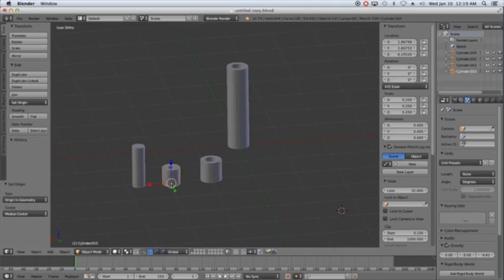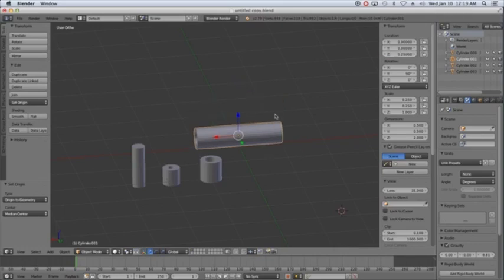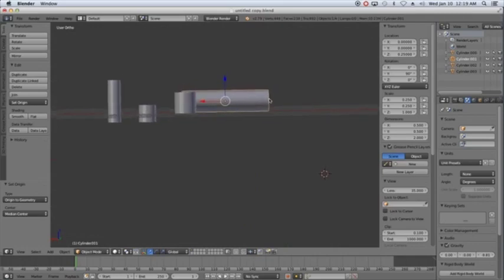You'll see why later. So I'm going to reorient this to be horizontal, so it's the same as it would be when you're using it. I'm going to come over here to this rotation menu, and rotate it around the y-axis. So I'm going to click the y-axis, 90 degrees, rotate it around. All right, now I'm going to put that at the origin so it's easier to deal with. It's already in the x and y coordinates of 0 here, but if I put this at 0.25, half of the diameter, then it's going to be sitting at the origin right on the XY plane. A little easier to deal with that way.